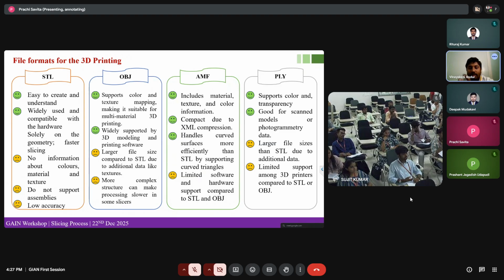While less common in general prototyping, it is a standard for research and scanning-heavy workflows. Where you are using scanning, this file format is used more. PLY's strength lies in its flexibility, because 3D scanning often introduces sensor noise, and PLY supports the storage of data confidence values directly within the vertex properties. This allows researchers to distinguish between high precision data and interpolated points.